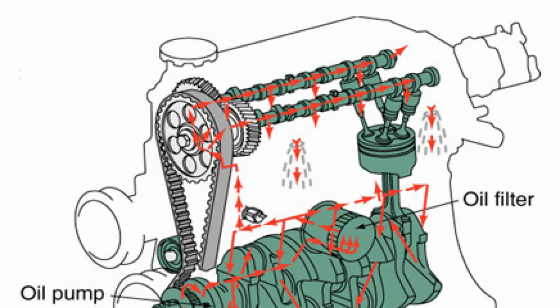At the same time, powerful engines use a dry crankcase system, in which a separate tank is used for intermediate storage of oil and the crankcase sump remains dry. Such a scheme allows to get rid of the dependence of pressure in the system on the level of liquid in the crankcase and the spatial position of the oil intake, which takes place in conventional lubrication systems.